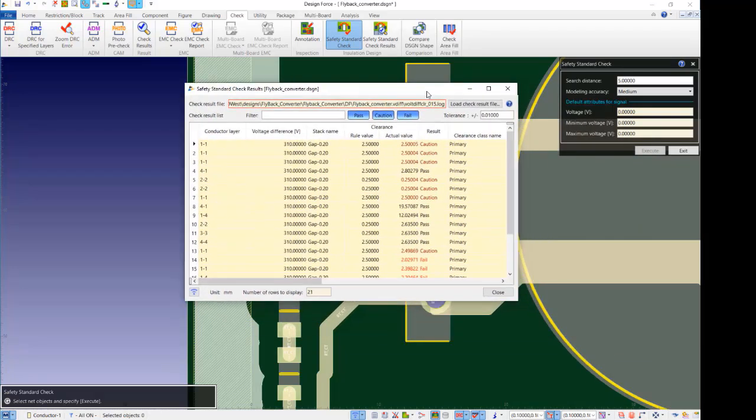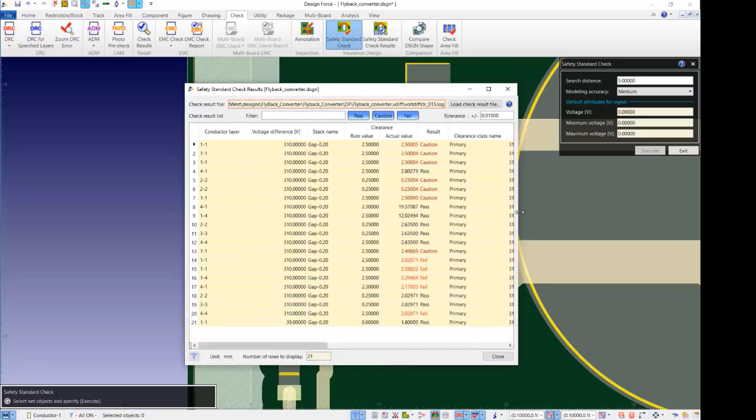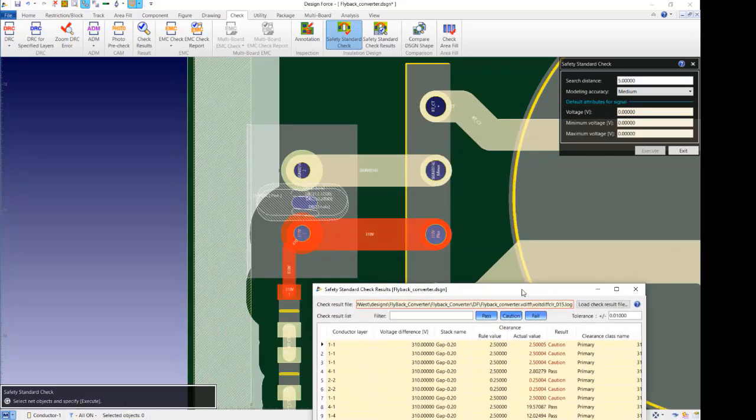Okay, now if I bring this up here, you've got my layer lists here, so it says from layer 1 to 1 or layer 4 to 1, for example. How is it now passing that condition that I've got? Okay, remember this is a 5mm spacing, so it's also potentially looking to other nets as well. It could be, looking up here, for example, to this net as well.